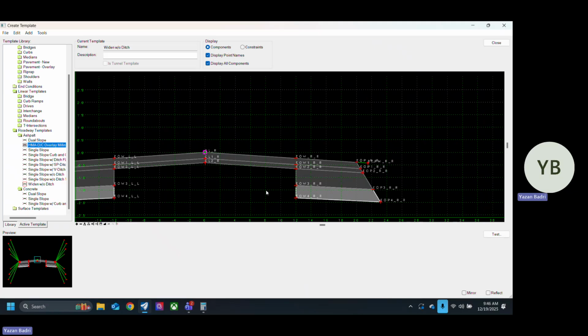So the question becomes, are we gonna keep that as 4% and the widening also becomes 4%? Or are we gonna do 2% at the widening? Or are we gonna overlay the whole thing and just make it all 2%? That's a design decision. That point, that's easier, but it's more.